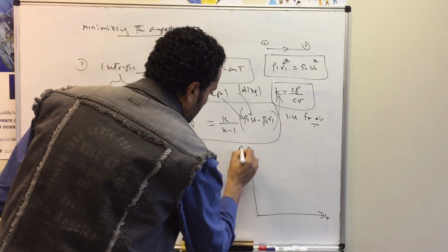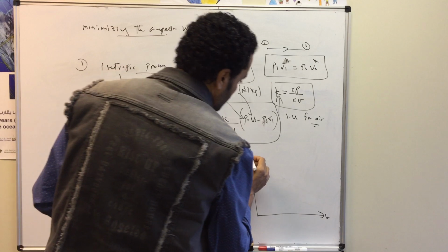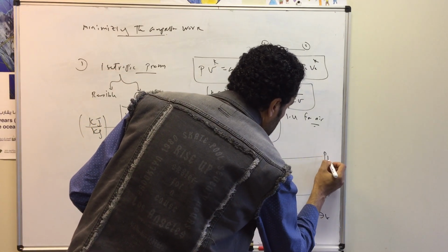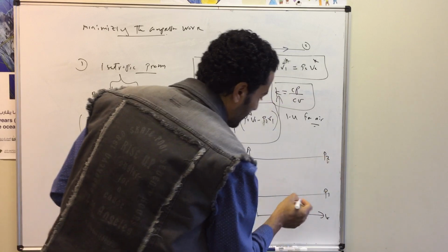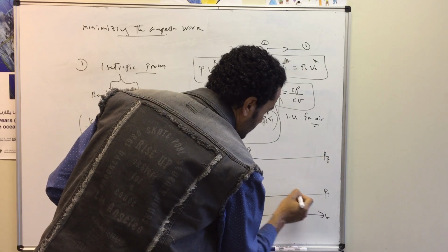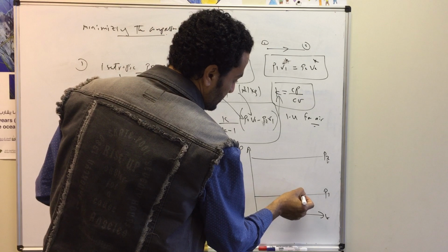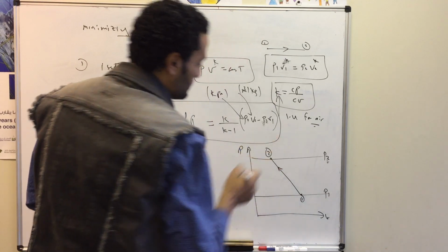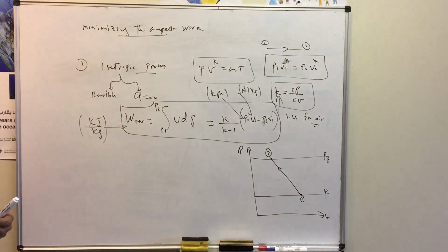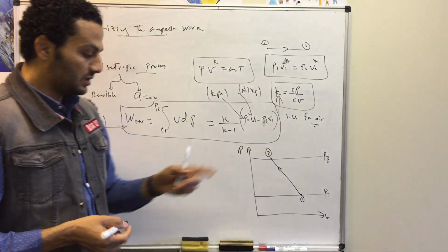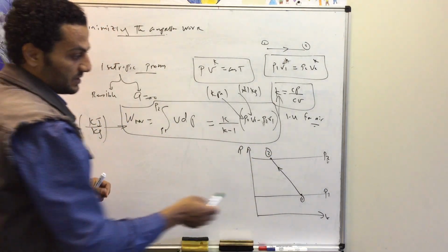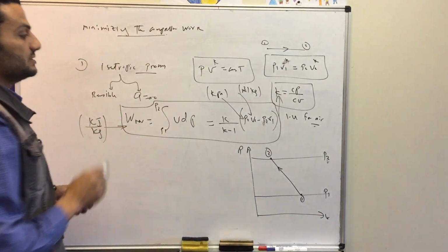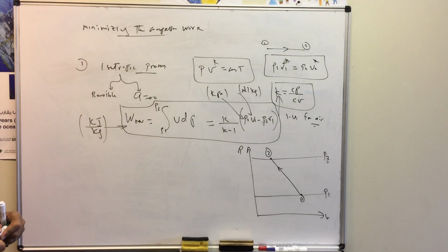Okay. This is a compression process through this compressor from pressure P1 up to final pressure P2. Let's say this is the input to the compressor. Due to the compression, the volume is being reduced through the system. So the gas is being compressed from initial state 1 up to the final state 2. As we said, the area under the curve on the PV diagram represents the work by the compressor in this case.